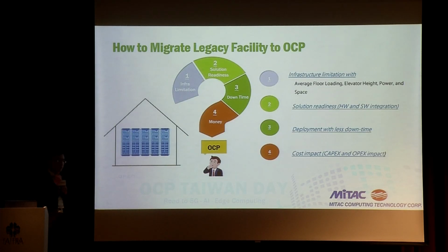So with those advantages of the OCP solution, how can we move it to the legacy environment? These are the 4 key concerns legacy data center operators have. So that is the gap. They could not adopt the OCP solution before last year, especially because of infrastructure limitations. You can see the average floor loading, and the open rack is too high for the traditional elevator. You cannot move it into the building.